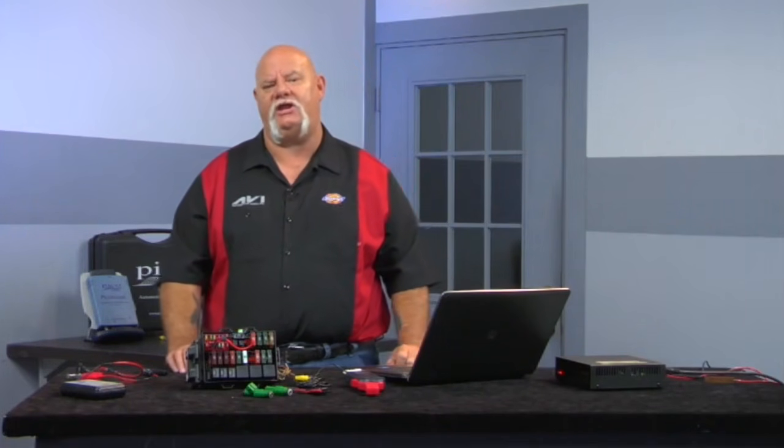Current limiting, because the computer decides to control the time that we pass current through the primary, or in some current ramping ignition waveforms, it'll look like someone took a straight edge and just cut the top of the point off of the current ramping. That means either if we have an external ignition module, or the PCM is the ICM, meaning the computer is the ignition control module, it will have the current limiting function in it.